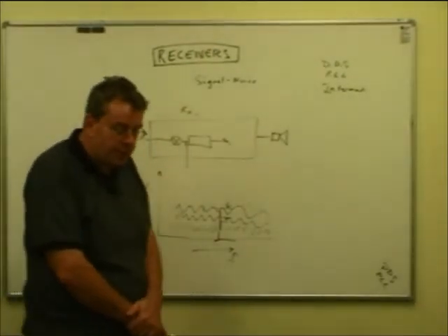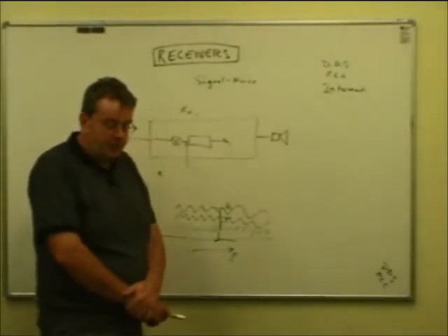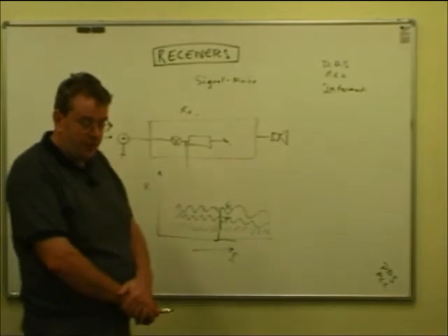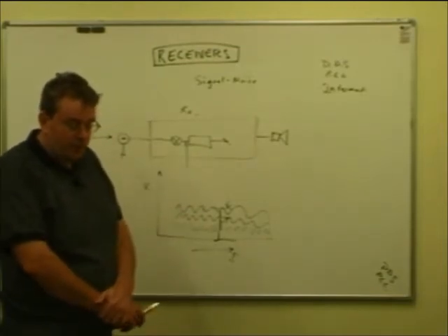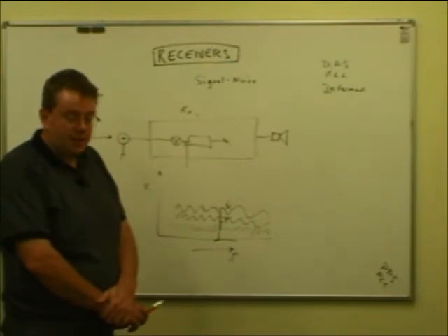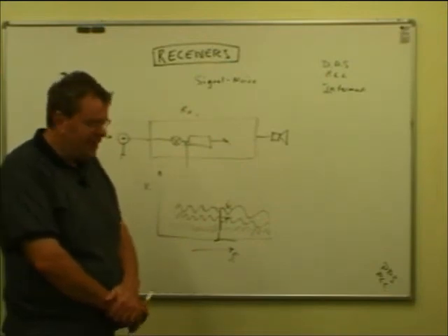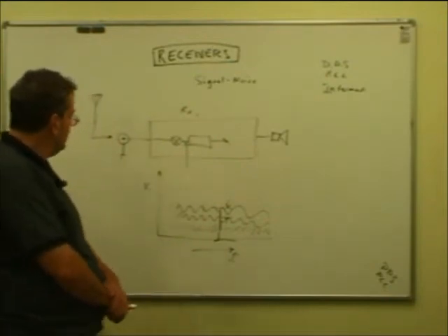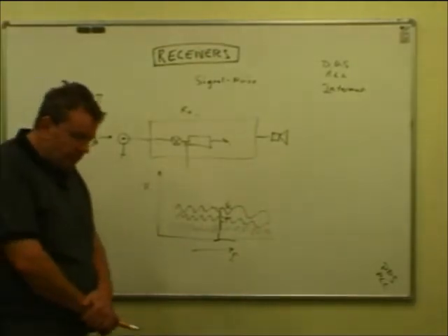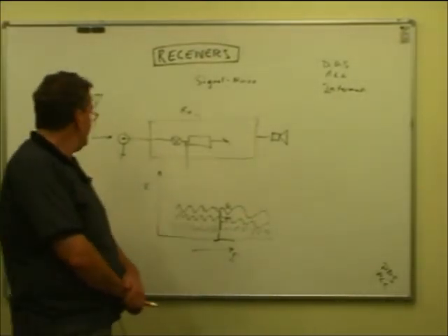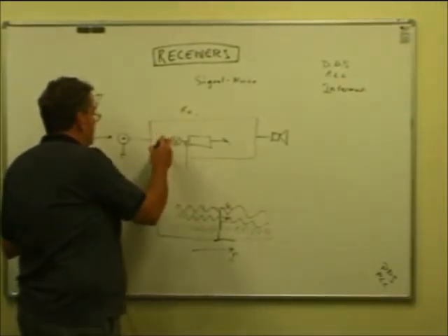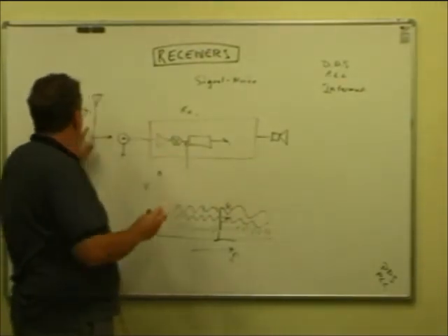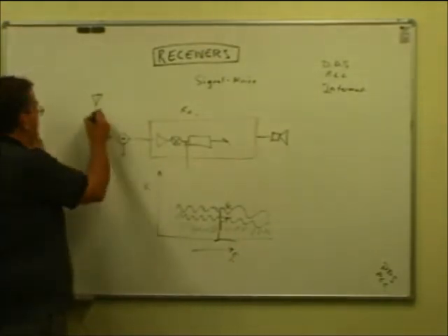When you're dealing with very weak signals at VHF, UHF and microwave, getting up over 1,000 megahertz, when people are bouncing signals off the moon and so on, or weak signals from trying to work DX, from one hilltop to another one miles away, the signals can be very weak. And people strive very hard to have very low noise amplifiers in their receivers. And one thing they'll often do is put an RF amplifier right up by the aerial.